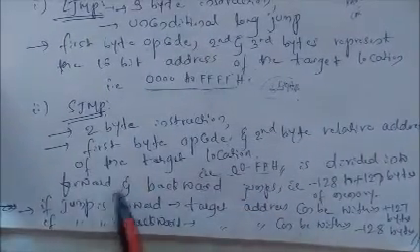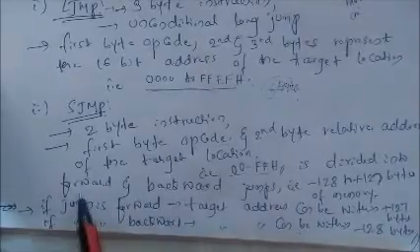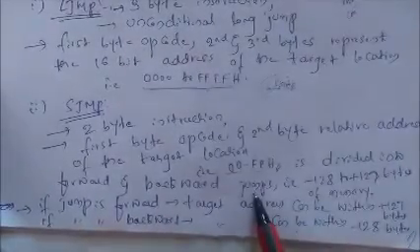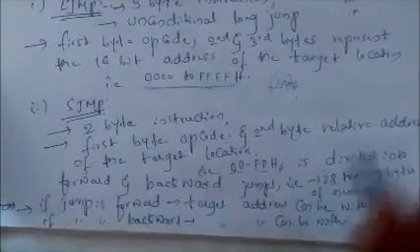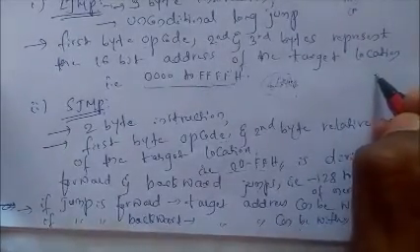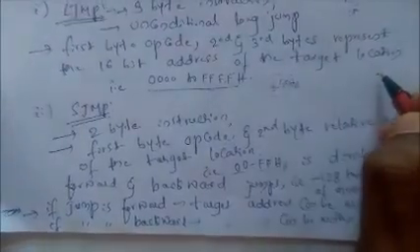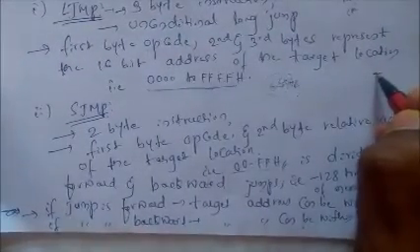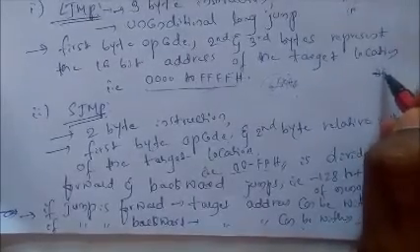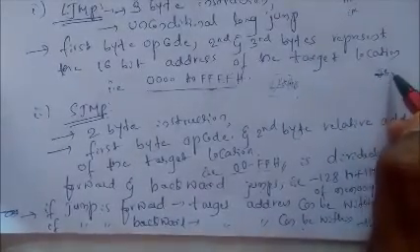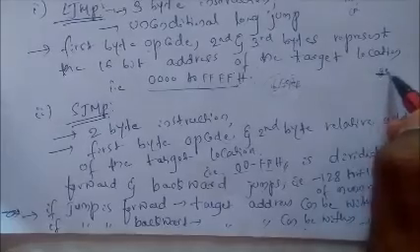Again, here they mention forward and backward jumps. Forward and backward jump means, if my execution line is here, my program is ready to execute some instructions here. I write some instructions here. The program counter has this value.